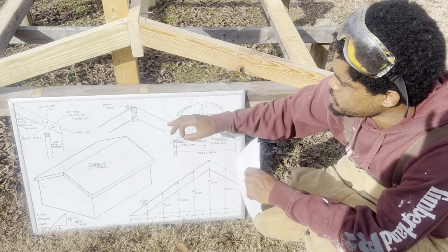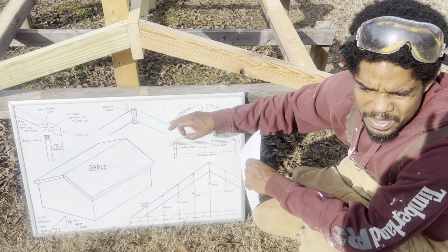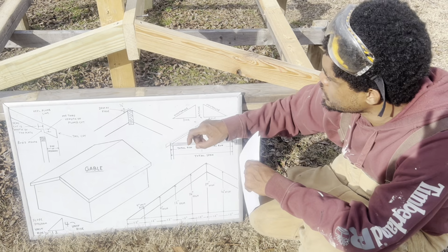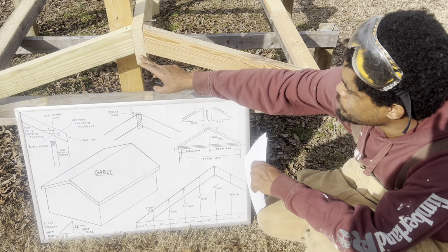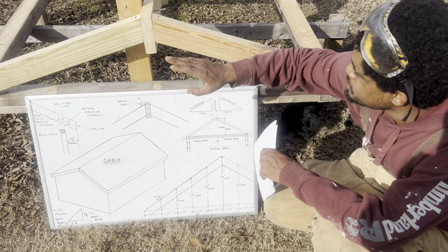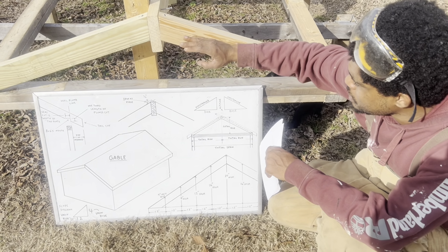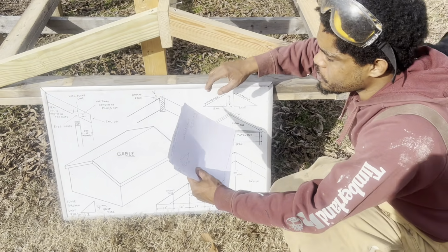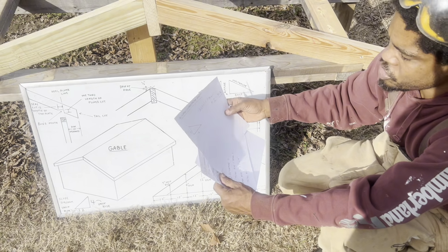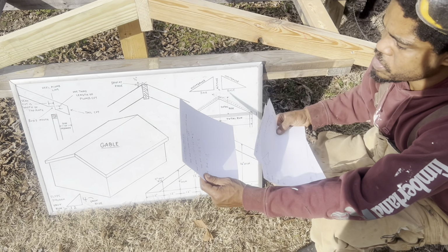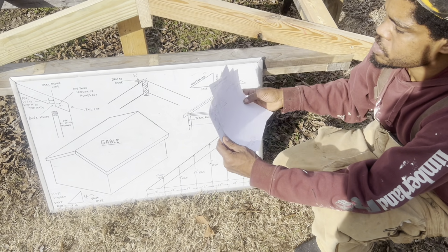Okay, we haven't talked about drop at ridge. We're going to talk about this in our next video, part 2. Also, I don't know if I mentioned, but I'm going to tell y'all again, with your ridge board, you want it to be wider than your common rafters. In our next video, we're going to be talking about calculating common rafters. We're also going to determine total rise, and we're also going to determine true rise. So watch out for part 2.